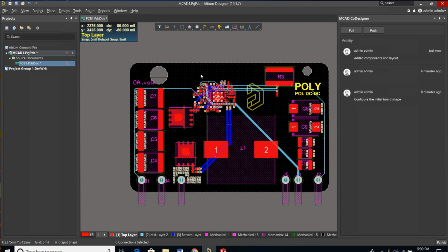We have a setting which tells which diameter should be kept as a limit for recognizing features as a cutout versus standard pads. So if the size of your feature is bigger than that limit, it would be taken into consideration as a cutout. Otherwise, it will be just a pad. Yeah, if it's the pattern.